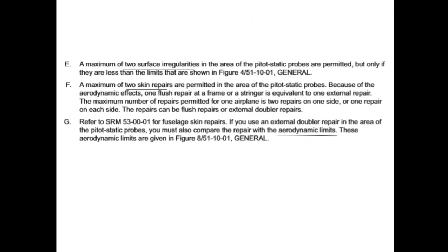A maximum of 2 surface irregularities in the area of the pitot-static probe are permitted, but only if they are less than the limit shown in the manual. A maximum of 2 skin repairs are permitted in the area. So if you have damage and you need to repair the area, and there are already 2 skin repairs in the adjacent area, then it's not acceptable. And you also need to refer back to the aerodynamic limit. Any damage requiring repair in the area, you must make sure the repair will not affect the aerodynamic limit.